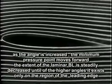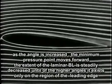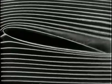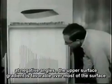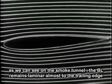As the angle is increased, the minimum pressure point moves forward. The extent of the laminar boundary layer is steadily decreased until at the higher angles it exists only in the region of the leading edge. At negative angles, the upper surface gradient is favorable over most of the surface. As we can see in the smoke tunnel, the boundary layer remains laminar almost to the trailing edge.